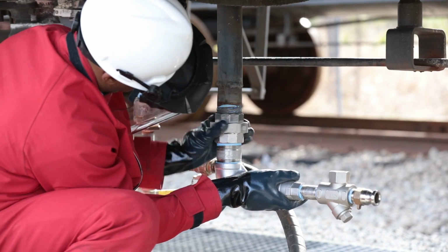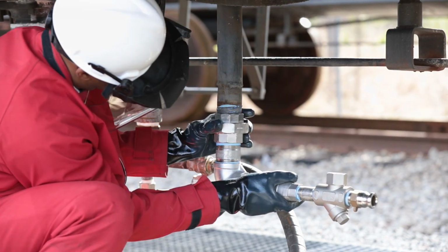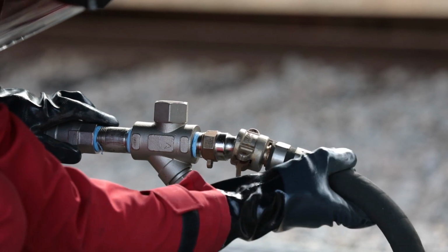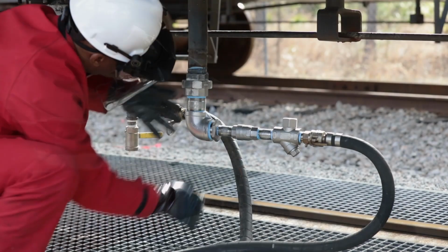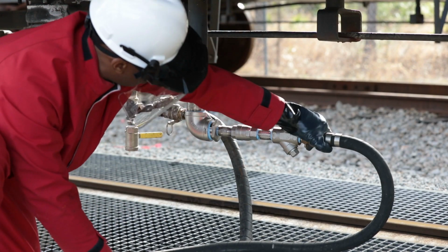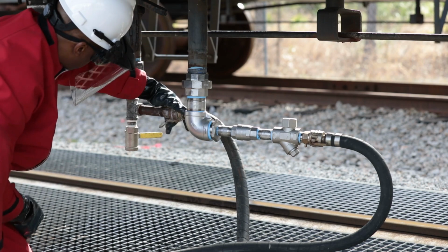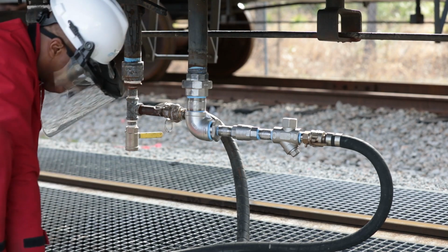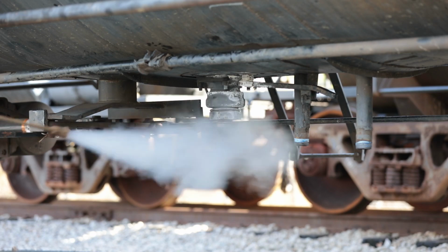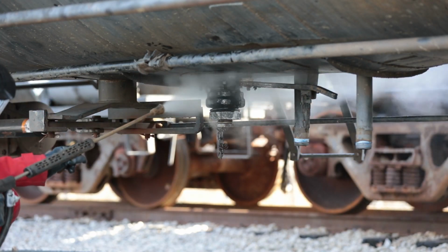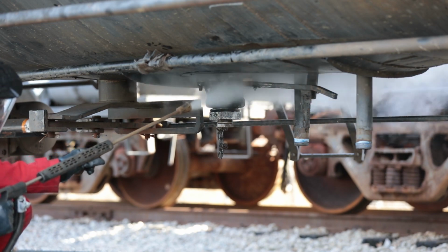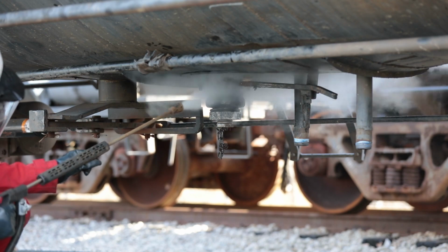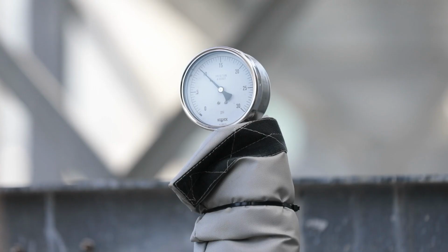A steam trap is connected to the other opening on the tank car's steam coils, and the trap discharge is connected to the condensate return system. The use of a properly sized and properly operating steam trap will give the user the fastest melting time for frozen caustic. Frozen caustic in a valve may prevent a valve from opening. A lance connected to a steam hose may be used to apply steam directly to a frozen car valve or inside a tank car for thawing. The steam is regulated to below 15 psig.